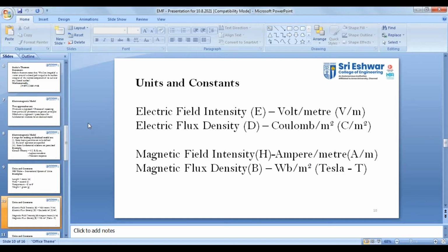And if I go to magnetic field, I will be having magnetic field intensity or magnetic pole strength, we call it. Its notation is capital H and expressed in terms of A per M, ampere per meter. You can see the comparisons. Electric field intensity means volt per meter, magnetic field intensity means ampere per meter. Then magnetic flux density, expressed in terms of Weber per meter square, or equivalent unit is Tesla. Capital T means Tesla. So these four parameters we will be using.